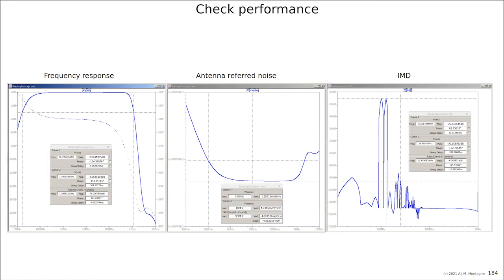So there's margin. If the weak nonlinearity would be exactly on the edge, you better work with this amplifier first, maybe in optimizing the operating point or in adding stages before you go to implement the bias sources, because maybe you need another structure to bias, and then all the work is done for nothing. And that is why structured design is perfect for lazy people, because you never do too much. You always do what you need.